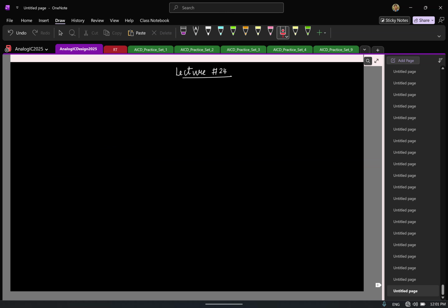So just to summarize the discussion on noise, it turns out any element that dissipates energy generates thermal noise. And for a resistor, although it's a noisy resistor, the way we model it is this: we assume that the resistor is noiseless. So let us say this is your noisy resistor. You do the same thing our parents do. We say that our resistor is noiseless. It is a nice noiseless resistor, but the noise is coming due to a hypothetical voltage source that is put in series with that. And the power spectral density of this noise voltage source, single sided value, is 4kT times R.